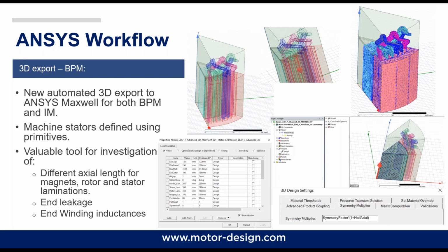But one point that I'd like to highlight is the symmetry multiplier. Since the 3D models may be computationally demanding, the script uses the symmetry of the motor and half of the axial length in order to reduce the computational time. As we can see at the right bottom side, the symmetry options are taken into account in the design settings properties. So the user will get the same result in less time.